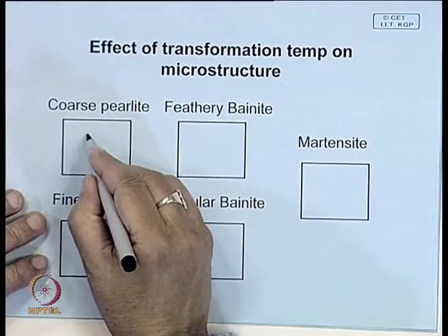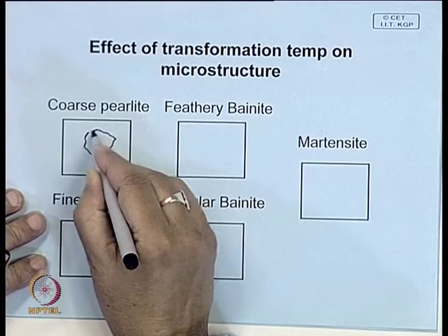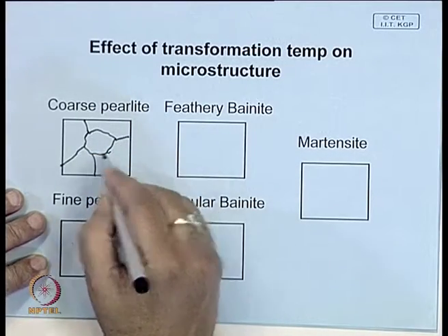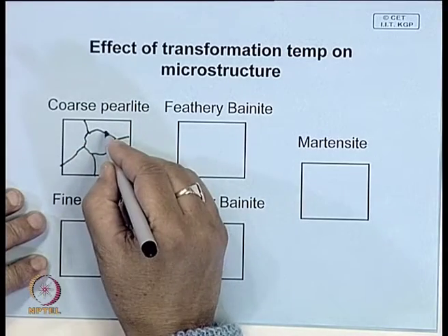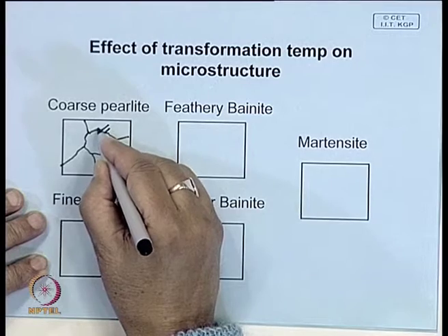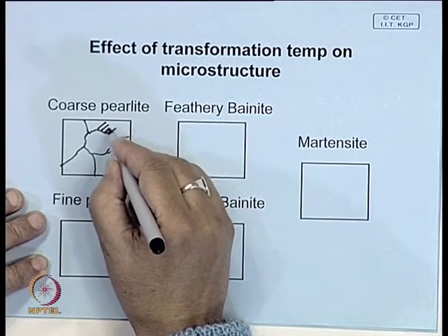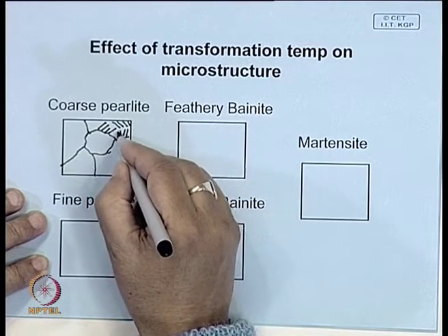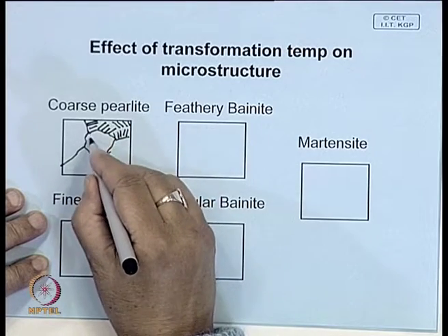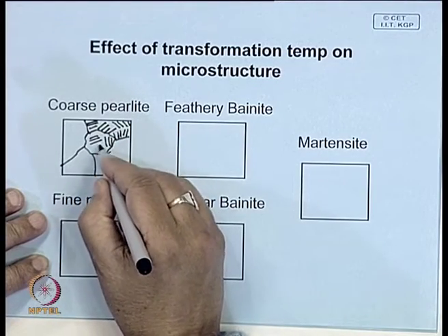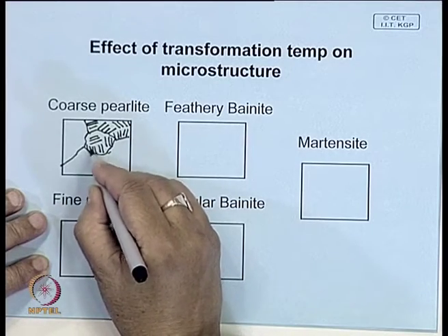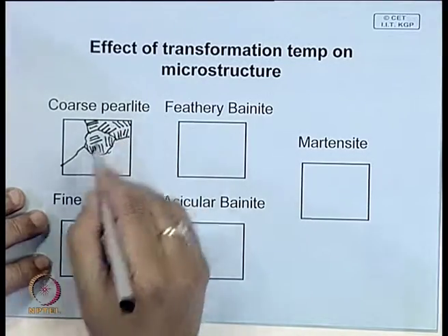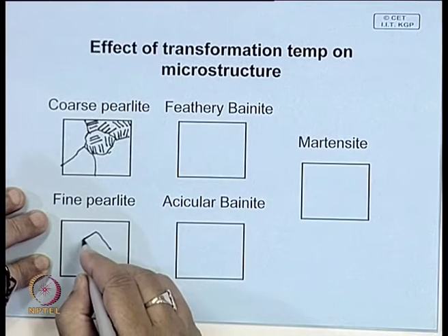Pearlite we have seen. Say, what happens in the austenite, these are the austenite grains. So, you have this austenite grain, and here pearlite starts forming a cementite nucleus, then these are cementite, and the white region is ferrite. So, this is how the pearlite structure will look, they will be lamellar, and this is how that entire area will be filled up. And the only difference is that in an optical microstructure, you may see that these pearlites are resolved,